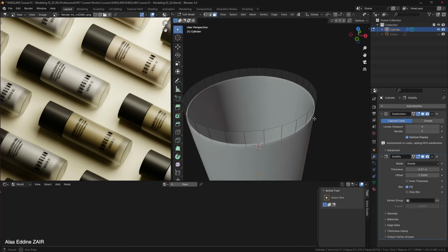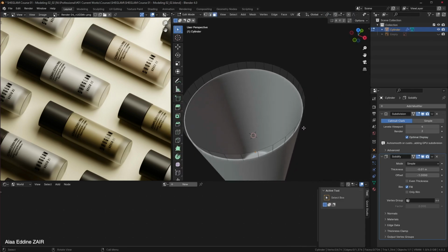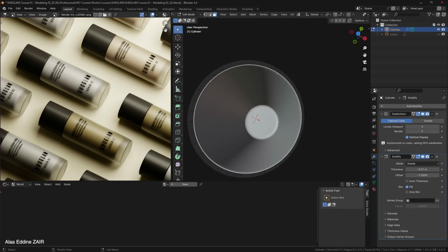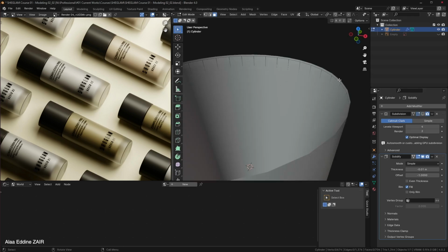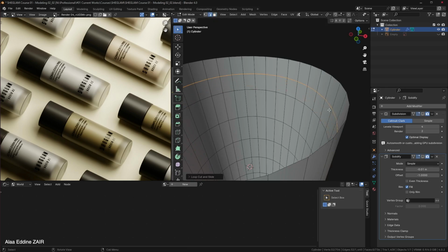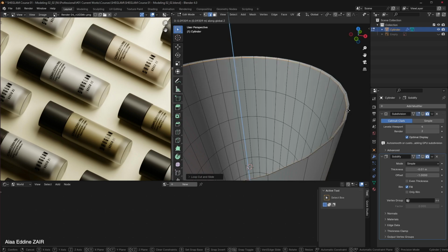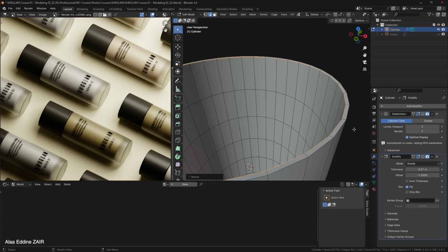The most important one is that when we extruded the top face down to create the inside, we didn't create a sort of edge there, and we can easily fix that by creating an edge loop in the inside. Move it up with G and constraining the movement to the Z axis, and then scaling a little bit.